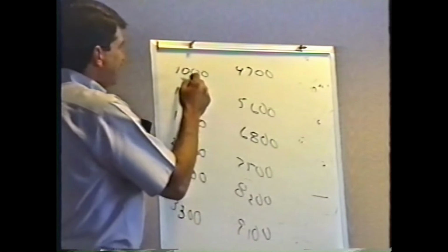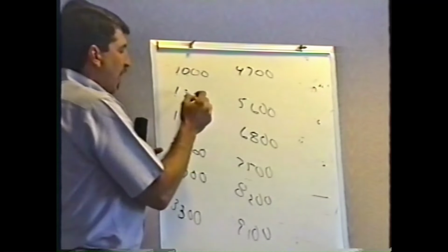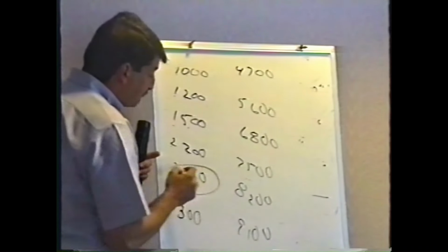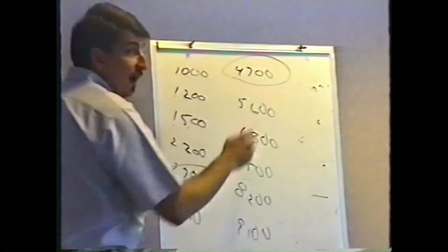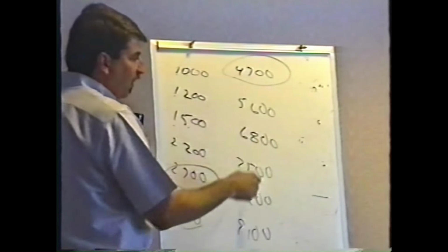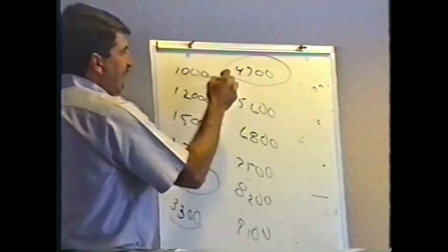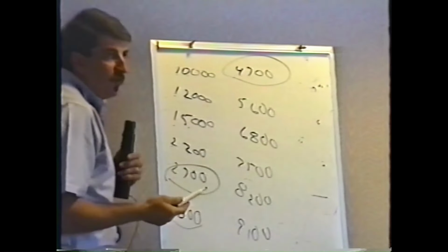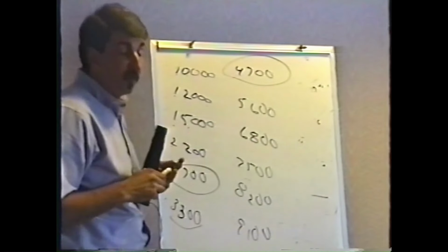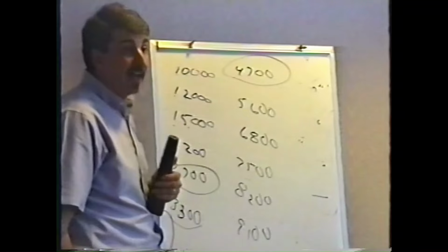So in other words, I see lots of brown, black, brown, red, brown, green, red, red, red, violet, especially common. So is yellow, violet. Very common. I see orange, orange, and so on. I see these combinations, and then we just change the multiplier band. So for instance, I see a brown, black, red resistor. Well, that's really familiar to me. That's a 1K. We use those a lot.